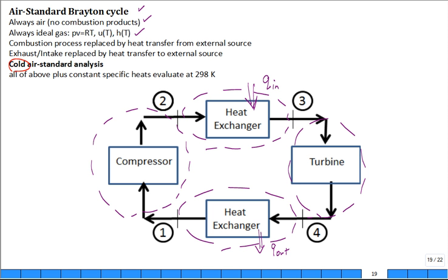Professor, are you ever asked in your office to please explain why we have delta H's instead of delta U's? Auto and diesel, it's almost all delta U's. Here you have all delta H's. That's why. It's an open system analysis. You have the change in internal energy as well as the change in flow work, the PV term, when you have a control volume. So this work into the compressor is, do the first law, H2 minus H3.